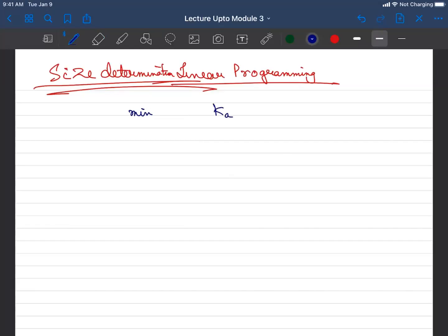Because you know that if you can build an infinite size dam, it is always going to make sure continuity is satisfied, but who is going to pay for it? So you want to minimize that. What are the constraints? Subject to: the active storage should always be less than or equal to maximum. Makes sense.